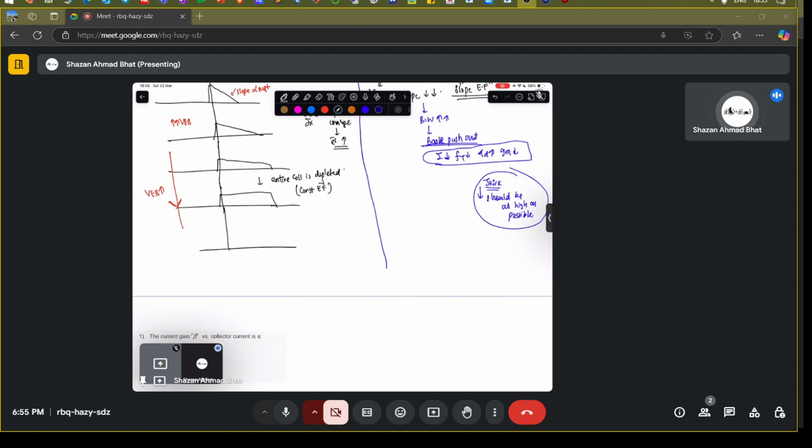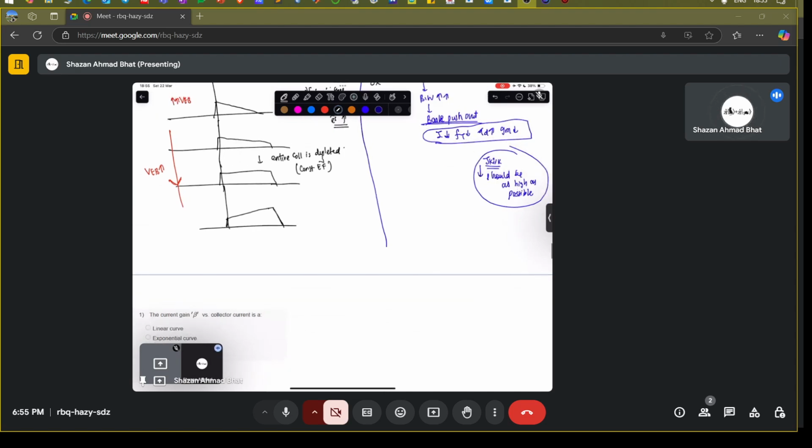At a moment, you see that you have a total inversion in the direction of the electric field, or I should say, the slope of the electric field. It becomes negative. So there is a flip in the slope. Why does it become negative? Because now the −J/(q·v_sat) term dominates over the +N_D⁺ term. So this becomes large, and you have a huge negative slope coming into the picture. So ∂E/∂x becomes negative.